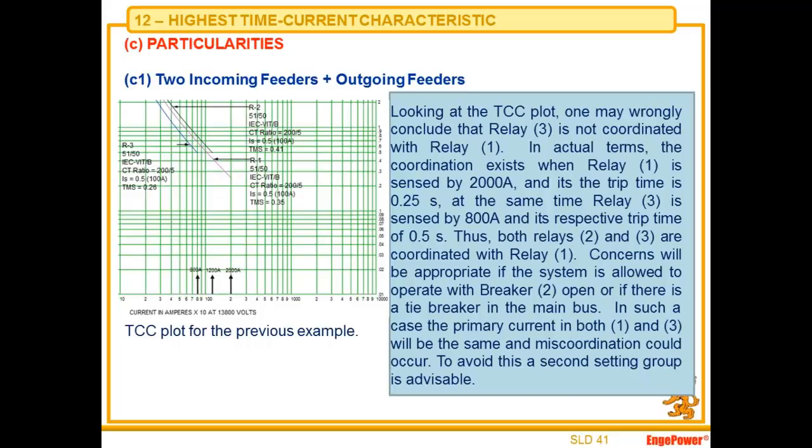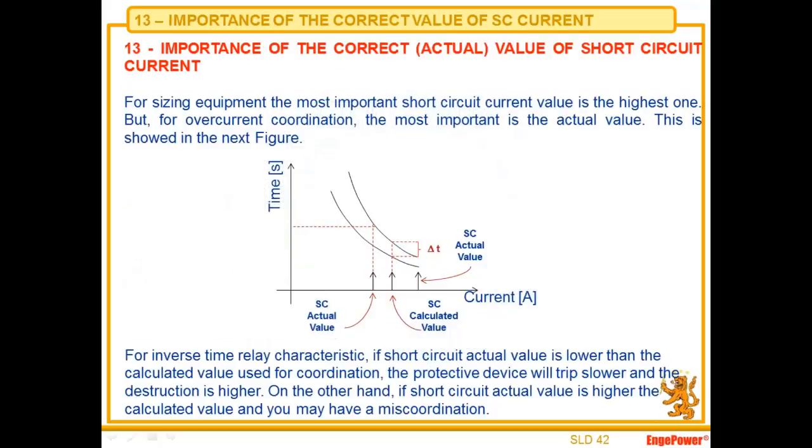Because if you open the breaker, the incoming will see the same current as the outgoing. The coordination point will change. So the time dial will change. Importance of the correct actual value of short circuit current.